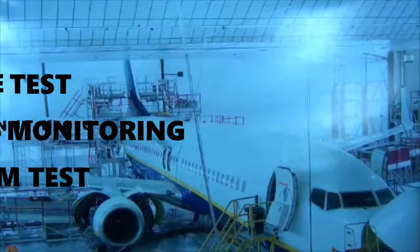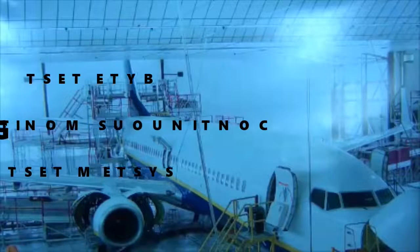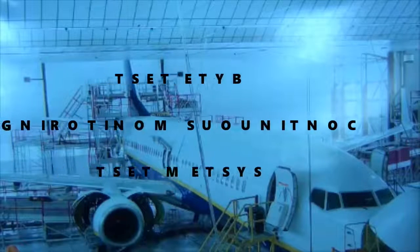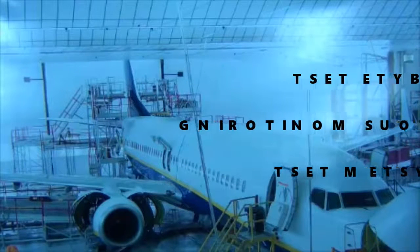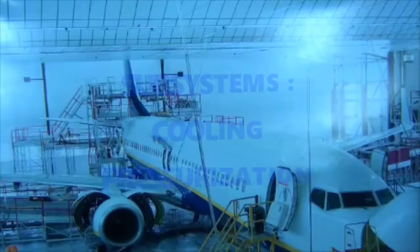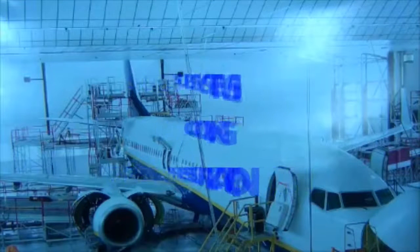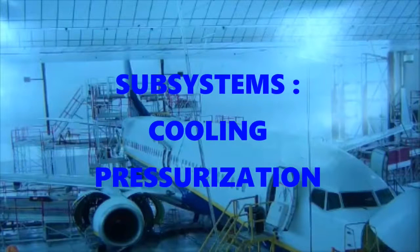All right. So that covers session 2. I was talking about the cockpit and cabin. That's what's controlling the conditioned air into those areas. Okay, it's going to be your zone controller, and of course you got your pack controllers, one for each air conditioning pack. And what do these packs look like? What comprises the pack? Okay, that's all the different components that I just covered, with your condenser, your water extractor, your primary main heat exchanger, right? Your air cycle machine's really big. Main component on the air cycle machine is going to be that shaft where you have your compressor on there.